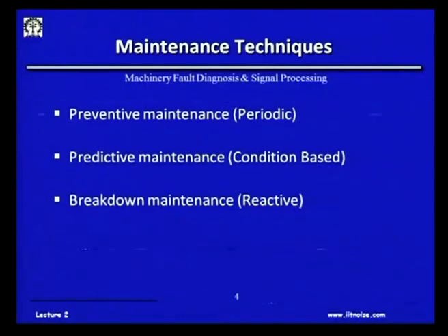So, by certain algorithms I can say whether my machine is going to behave the present way, or its condition is going to be okay or it is going to be worse. I can find that out from the data stored in my database from the previous conditions of the machine. So, predictive maintenance or condition based maintenance always depends on the present condition, sometimes on the past condition of the machine, but the machine's condition needs to be known to do maintenance.